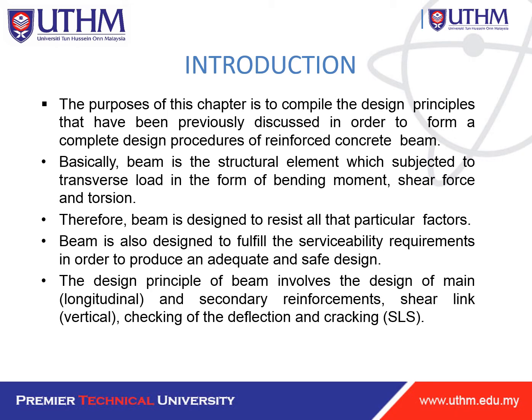So design principles of beam involve the design of main, which is longitudinal, and secondary reinforcement, shear links for the verticals, and checking the deflections and cracking.